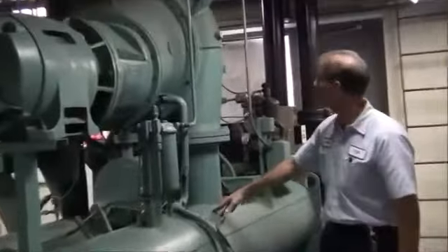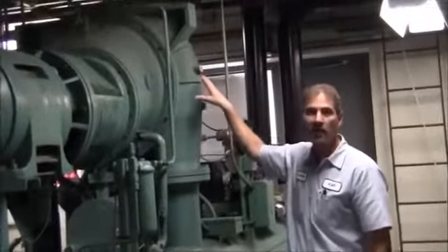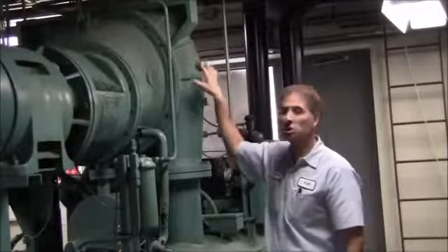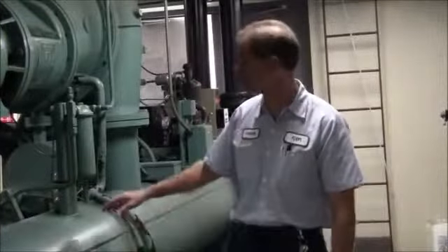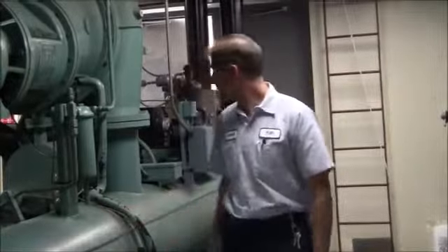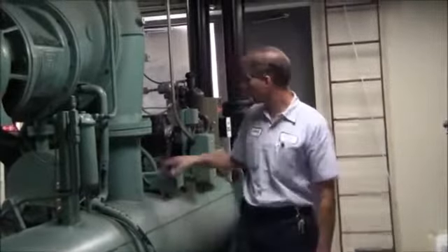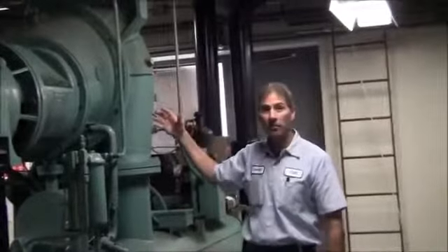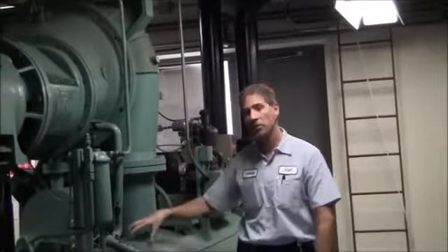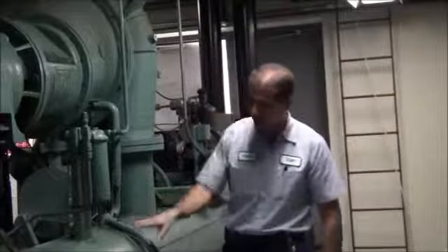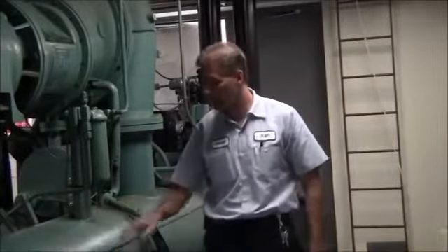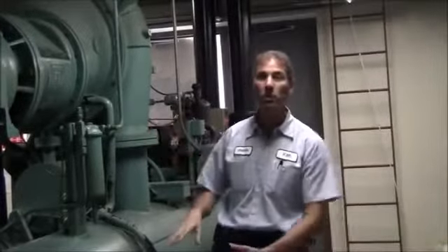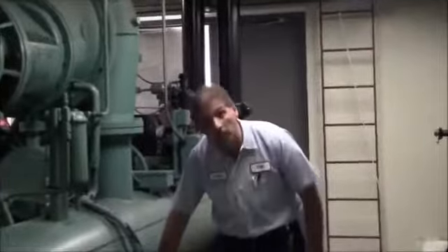Now this particular chiller is a high-speed centrifugal. So this here is the centrifugal compressor. All right, so here's an explanation of the refrigerant flow in the chiller. What happens is the refrigerant comes out of the compressor and it goes down into the condenser. The condensing water, which is in the tubes of the condenser, will allow the refrigerant to condense from a vapor to a liquid, which is collected here at the bottom.